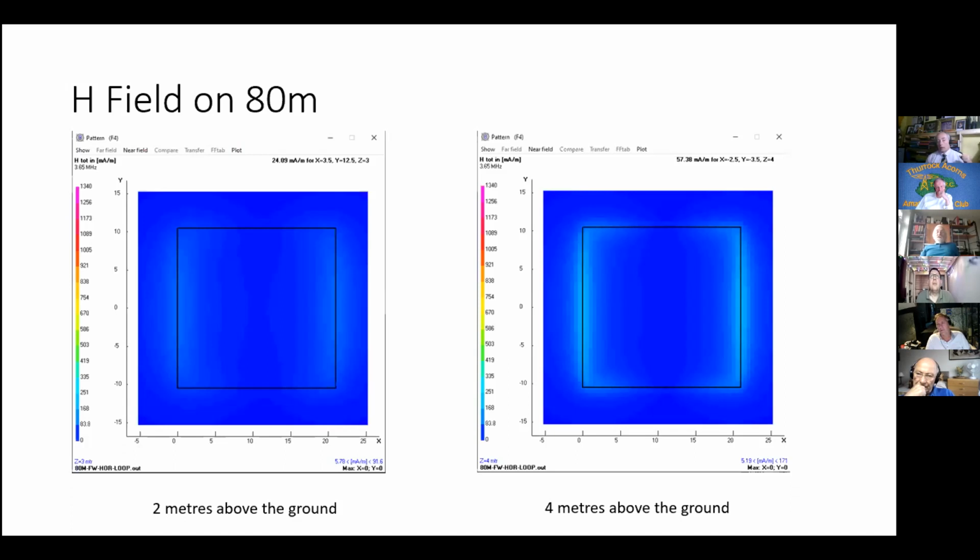The sort of antenna that I was inquiring about was the trap vertical type of thing with tuned radials. Yeah, so those will probably have significant fields around them, so they would be similar to my model of the 160 meter antenna with electrically short radial. So very much a rule of guesswork, as it were. They're going to need to be like 4 meters up, kind of thing. I figure so. Just as a very rough idea.